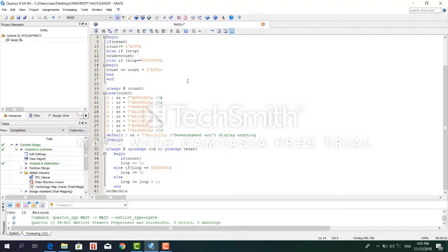So how about the 7 segment, Mr. Wanan? Like I said before, the counter will go on from 0 to 7. These numbers represent segments A to G. This 7 segment is active low. So when it is 0, the LED will light up, and when it is 1, the LED will be off. This means when the counter is 0, it will produce A, when the counter is 1 it will produce small a, and so on from A to small d. Am I right, Mr. Wanan? Yes, to small d. Other than this condition, the 7 segment won't display anything.